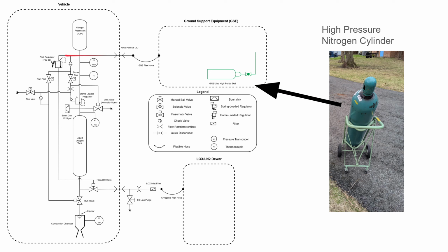We wouldn't be able to connect it directly to the COPV. This would be dangerous because the COPV is only rated to 4,350 psi and not 6,000 psi. So if connected directly, that would be dangerous because it would be above the rated pressure of the COPV. So the first thing we need is an ability to regulate that pressure down from 6,000 to 4,000, or whatever